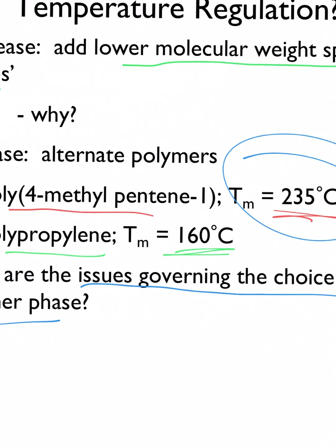So the issue is that you have a coupling agent, say it's a carboxylic acid, that works great for polyethylene, but now you say, well, I'm going to take that and heat it up to 100 degrees higher. That coupling agent may fry at those higher temperatures. And so now you may have to go back to the drawing board and say, oh, well, not only do I need a different polymer, I need a different coupling agent. And that can be a pain in the ass.